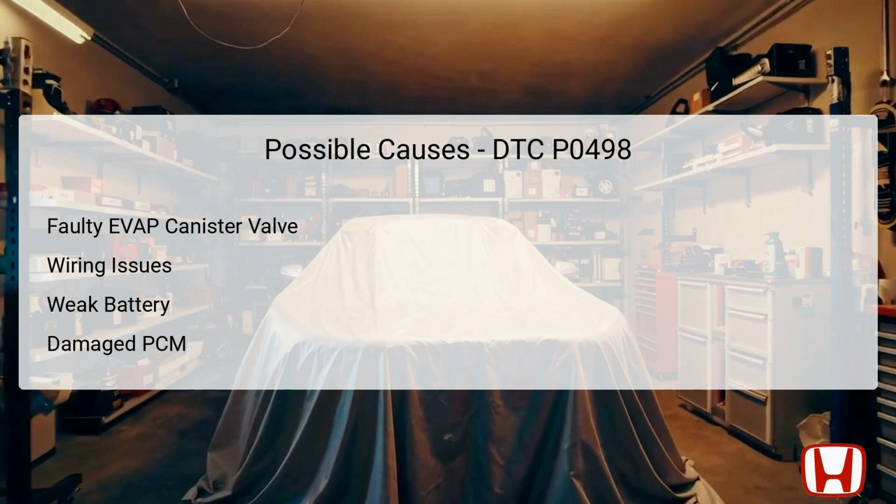Additionally, a weak or failing battery could result in insufficient power being supplied to the valve. The Powertrain Control Module, PCM, which controls the valve's operations, could also be malfunctioning, resulting in erroneous voltage readings. Hence, a comprehensive check of these systems is crucial for accurate diagnosis and resolution.